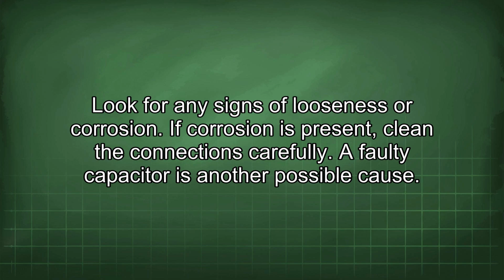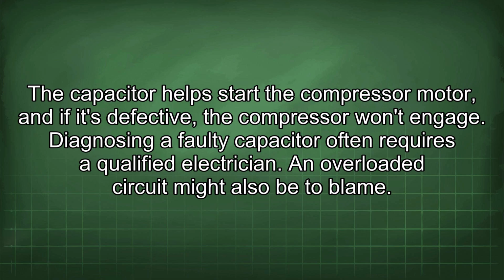A faulty capacitor is another possible cause. The capacitor helps start the compressor motor, and if it's defective, the compressor won't engage. Diagnosing a faulty capacitor often requires a qualified electrician. An overloaded circuit might also be to blame.